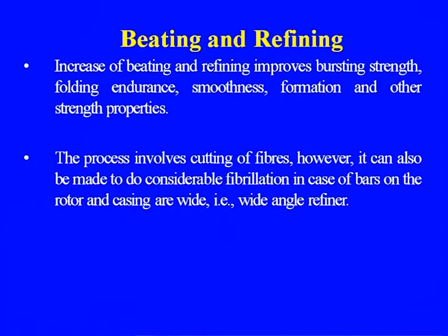Now let us come to the stock preparation, beating and refining. This results in an increase in the bursting strength, folding endurance, smoothness, formation, and other strength properties of the paper, which is very important. The process involves cutting of the fibers. However, it can also be made to do considerable fibrillation when the bars on the rotor and the casing are wide, that is, wide angle refiners.